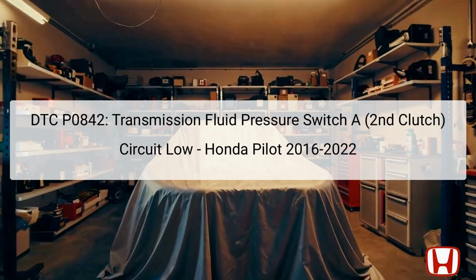The DTC P0842 indicates a fault in the transmission fluid pressure switch A, second clutch, circuit, specifically a low signal condition. This DTC is generated when the engine control module, ECM, also referred to as the powertrain control module, PCM, detects an issue with the transmission fluid pressure switch, responsible for monitoring the hydraulic pressure in the second clutch of the automatic transmission. The switch works by varying the resistance in response to the fluid pressure, signaling the PCM when adjustments are needed for shifting gears.